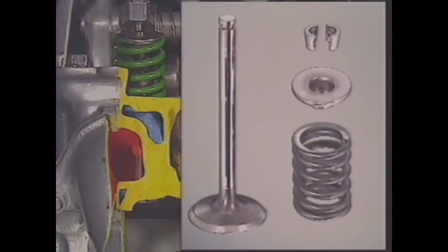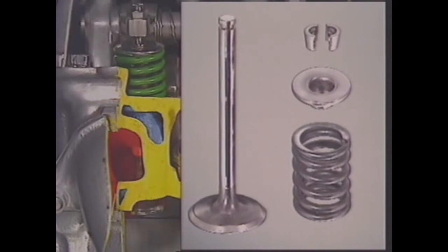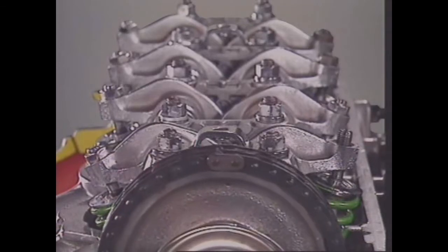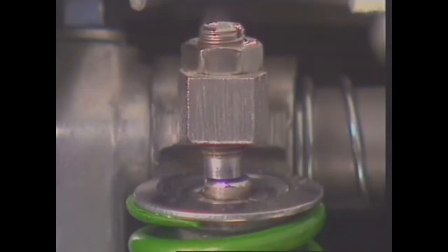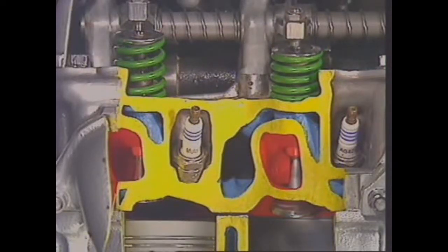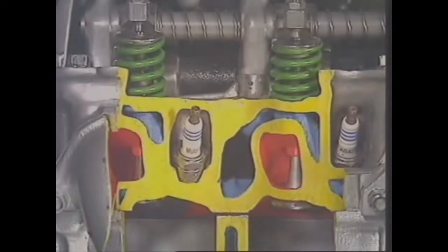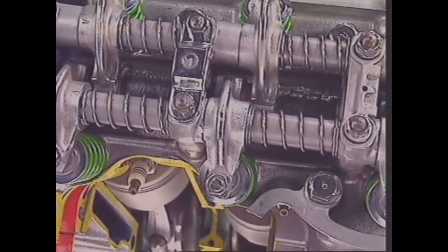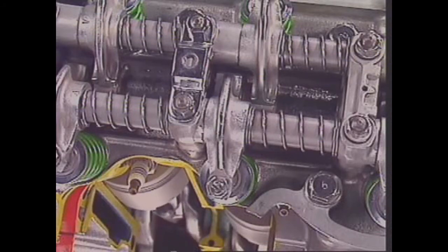The valve is held in place by a valve guide with a spring on its stem. A rocker arm is attached to a stationary shaft that allows the arm to pivot. The rocker arm compresses and releases the valve spring so that the valve opens and closes. The valves need a system to control how they work. This is done by using cams. A cam is a lobe on a shaft. It's specially shaped to open the valve, hold it open and let it close.